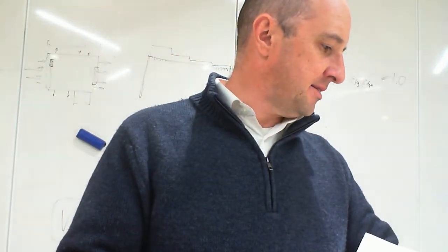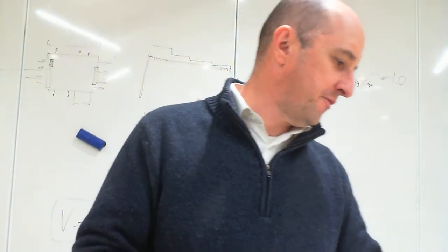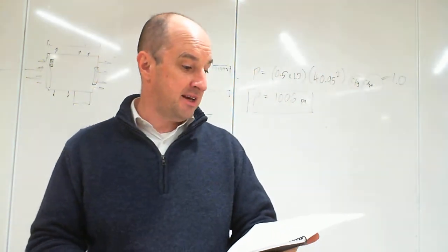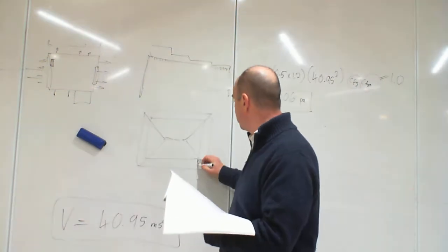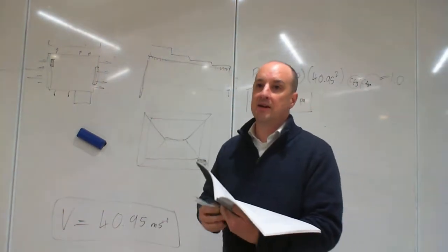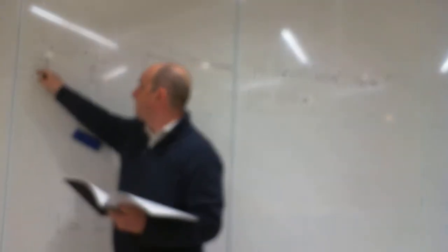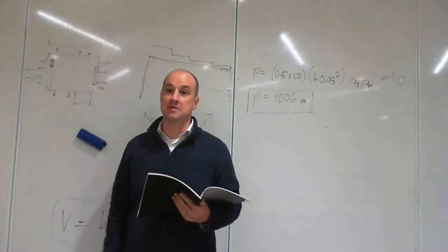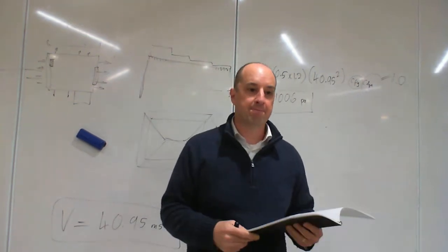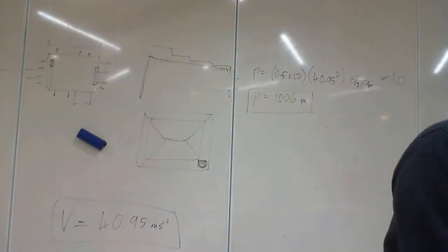And there are things like negative pressure, upwind corner roof with pitch less than 10 degrees, 3.0. Okay, that's that corner I was talking about. So you have to allow for force on the whole structure, and then you have to allow for higher amounts of force on small parts of the structure as well. Okay? All right.